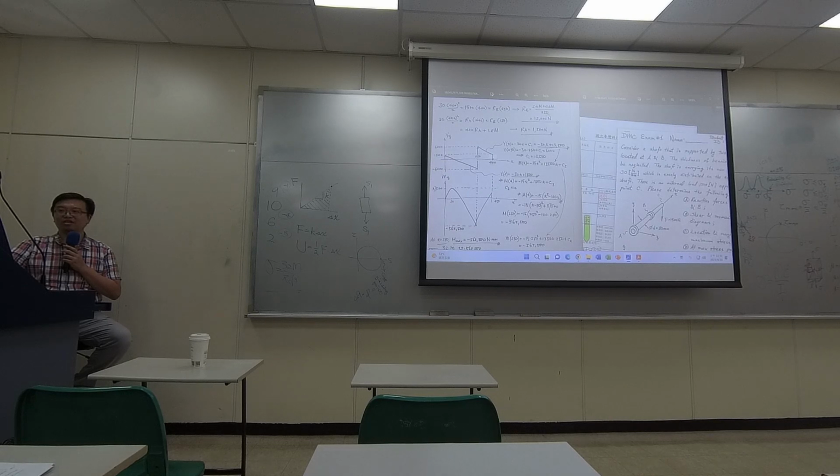Okay, then I have another reaction force at B going up. If my calculation is right, then it's 12,000. So it's going up 12,000. That's why you got 6,000 here. So my mistake could only be coming from an incorrect balance of moment. You guys can double check, maybe I made something wrong here. But if I'm right, then the shear diagram should look like this.